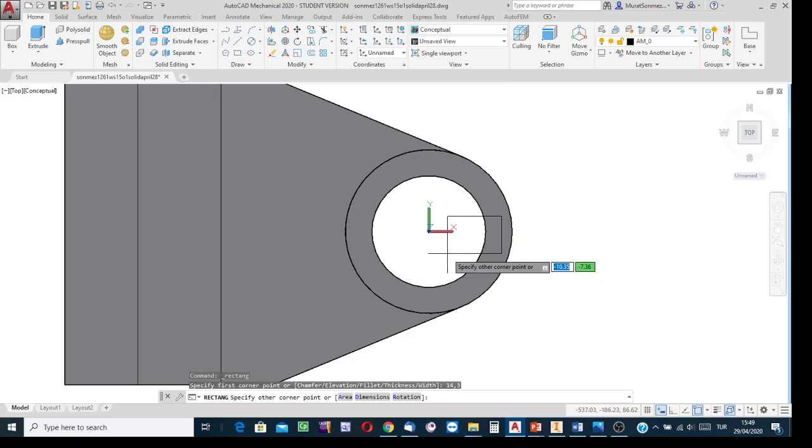How about the opposite corner? For the opposite corner abscissa value, I don't know the distance from the corner to this circular boundary. But I know that if I create the rectangle with such a further extension, I can use the rectangle as the region to create the necessary rectangular prism. So as the abscissa value, from the box I see the order of magnitude.